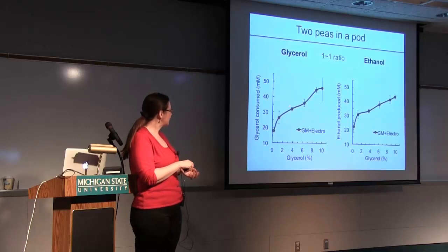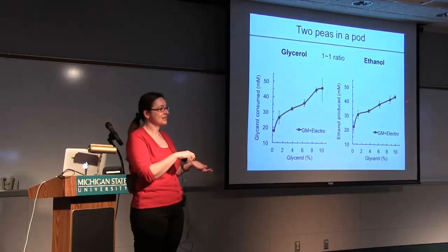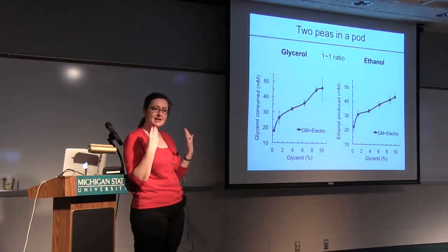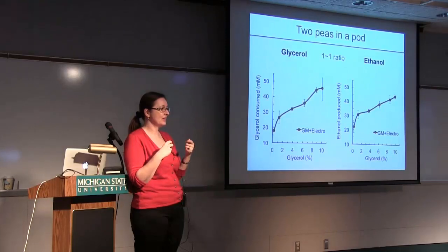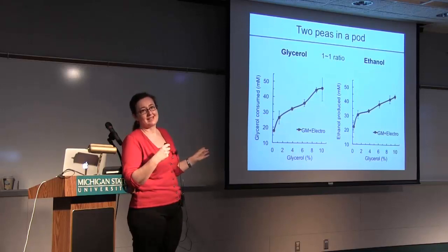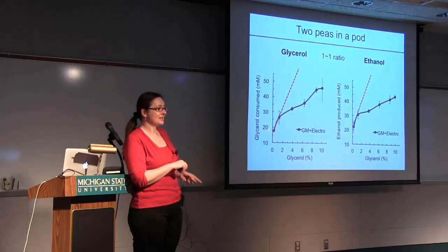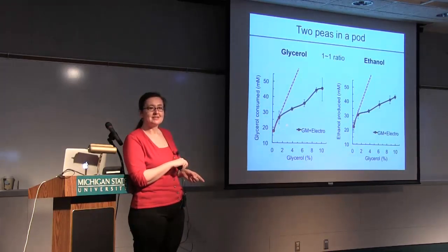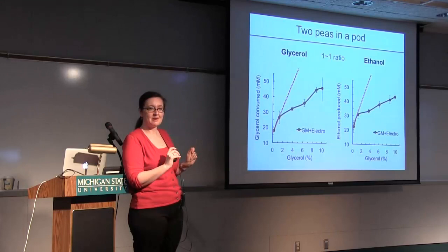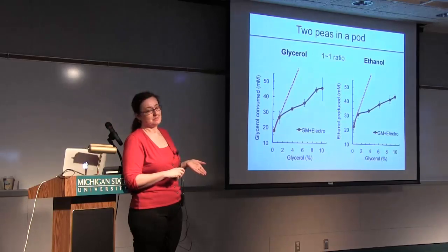As we increased the amount of glycerol we fed them, we increased glycerol consumption proportionally. And proportionally, we increased the amount of ethanol in a very close 1-to-1 ratio. Usually 90% of the glycerol was converted into ethanol, really maximizing the yields. But what I want to tell you is, although these results were great and very promising, look at the limitations. We started very well, but we could have done much, much better. In industrial processes, this is what you want, to push the process to the maximum yields possible. And we started to identify some things that definitely need improvement.